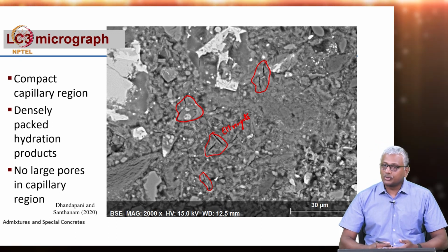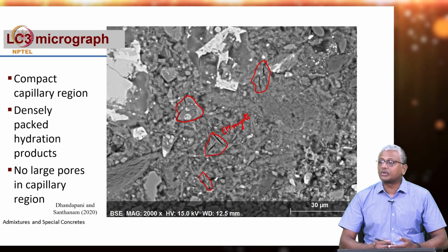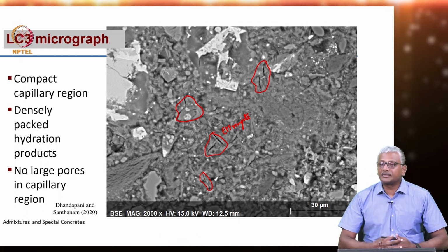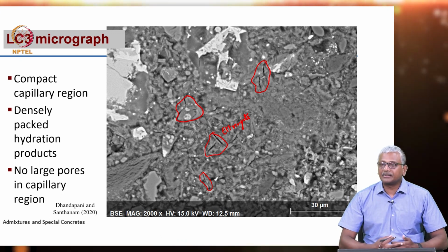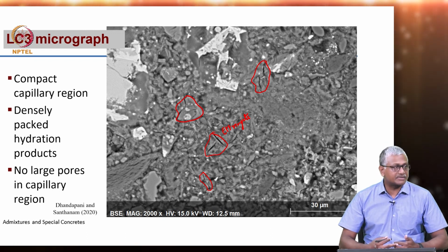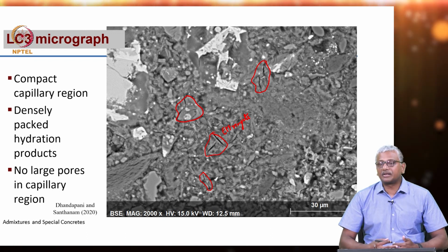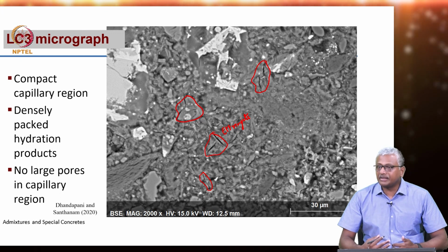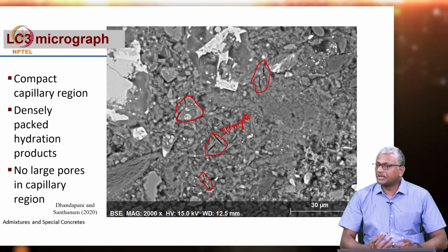Again, you can actually do the study instead of on cement paste, on concrete, and look at the region close to the aggregate to see the clear dense packing exhibited by concretes with mineral admixtures, and that clearly indicates the benefit of using mineral additives.